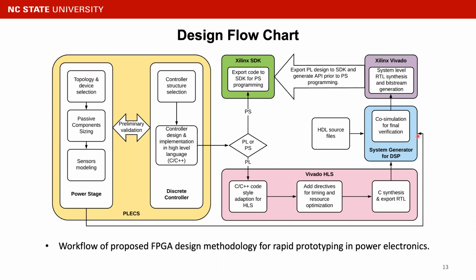Moreover, we can link our whole stage modeled in Plexim with this toolbox so that we can have a co-simulation for the final round of verification. After this, we can export all our design into the Xilinx Vivado environment, and then in this software, we will run system-level RTL synthesis and the bitstream generation.